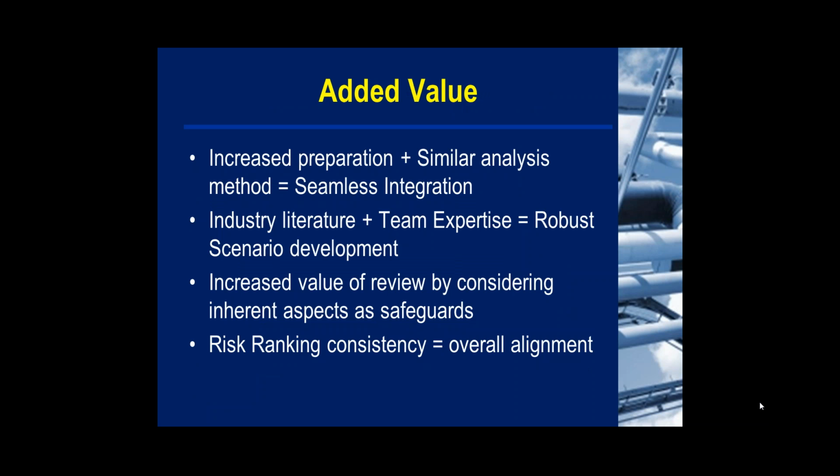So here's our sample scenarios. You'll notice it's very similar to a HAZOP worksheet, right? So as I mentioned earlier, you have your DM node and your deviation column, which includes a quick description and the operating parameters, and then your damage mechanism is included as the cause. The consequence includes a lot of detail, even including operating parameters and direct verbiage from API RP 571, and you'll see that the safeguards there are categorized. And we use different colors. We use blue for inherent and red for non-inherent to really separate and to make sure that categorization is shown.